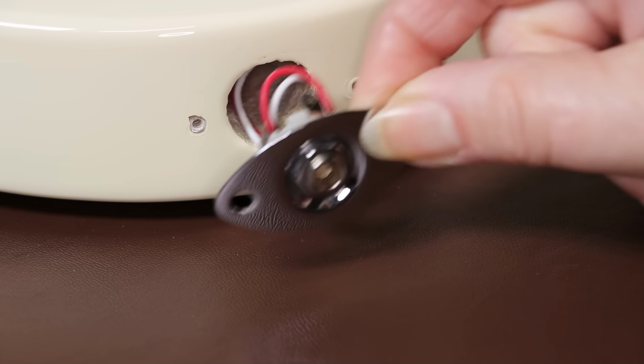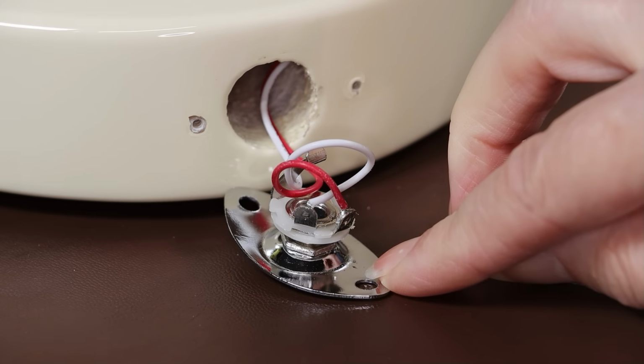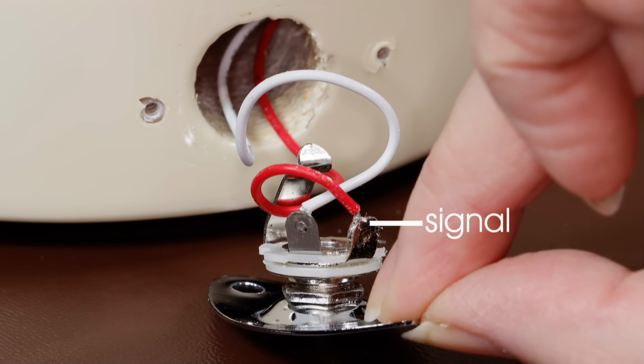Coming out of your guitar, there's just two wires. One is the signal wire, and the second wire is the ground or earth. And we want to use the ground or earth as the screening wire. And this means everywhere from the pickup right the way to the amplifier, we want to try and make sure that the signal wire is surrounded by the ground or earth.